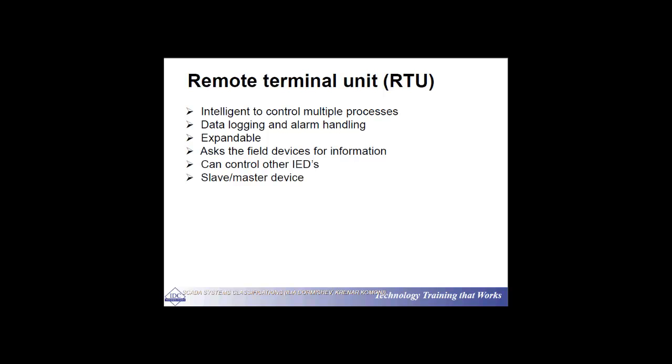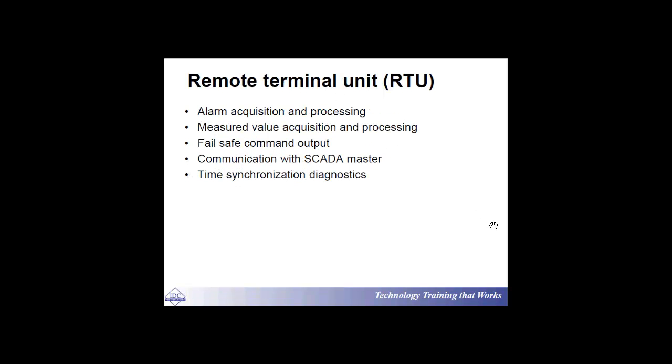All I'm saying is that I can define a master-slave relation in between. Therefore, the RTU is the first point of contact to do the alarm acquisition and processing, measuring values, fail-safe command, communication with the SCADA master station, and one of the main roles is to synchronize all these processes in terms of time.